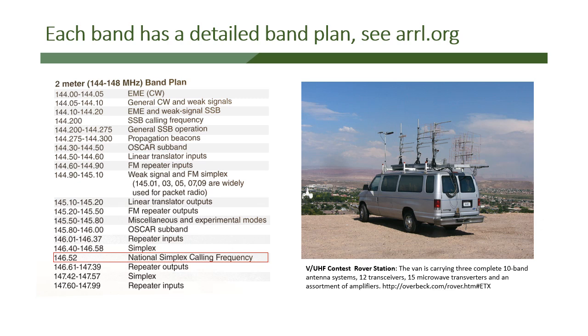And then we have areas for like SSB calling frequency. So if you want to do weak signal, single sideband calling in the upper sideband on 2 meters, you can do that. That's where the all mode transceivers come in. Then you would call 144.200 would be your calling frequency, which means I would call for a station to want to talk to me at that frequency.